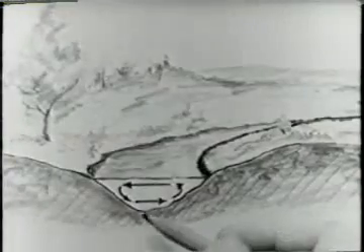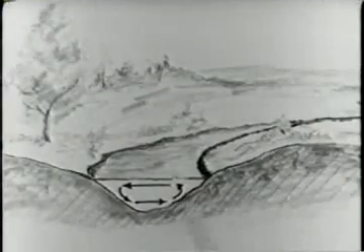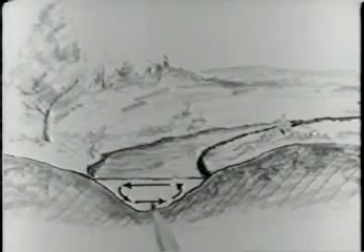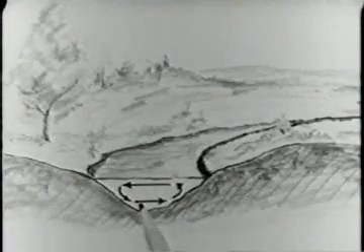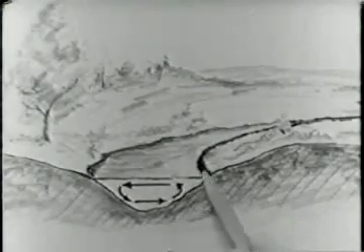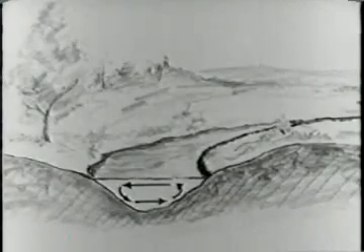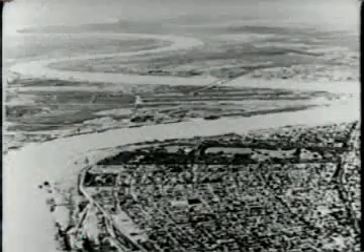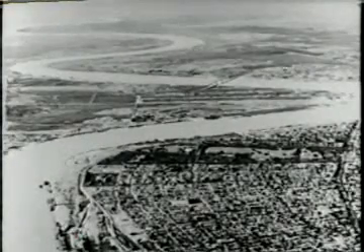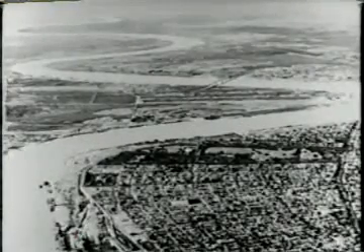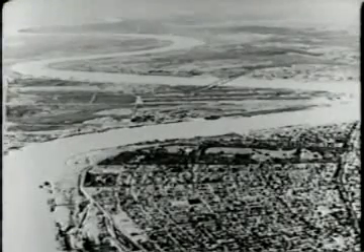Such secondary flows often occur when a channel is curved. When a river goes round a bend, the secondary flow erodes the outer bank and deposits sand and pebbles on the inner bank. This tends to make the bend get more bendy. Some people think that this is one of the mechanisms by which exaggerated cases of meandering occur.